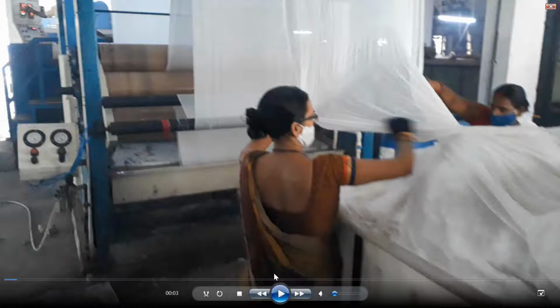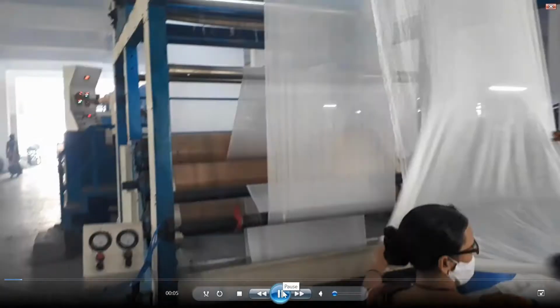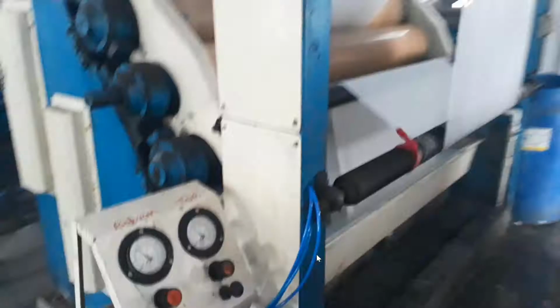It fixes the width and length of the fabric. This is absolutely a very important step, and stentor is very important where any processing is being done on any fabric. But particularly for polyester and nylon fabrics, heat setting is a very important process which decides the stability of the fabric. Now here, fabric passes in open width, and it is loaded in open width form in the trolley,